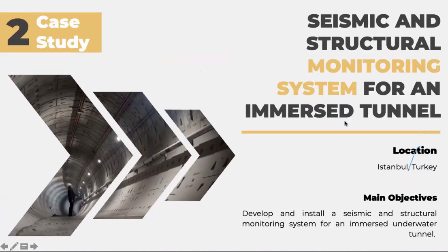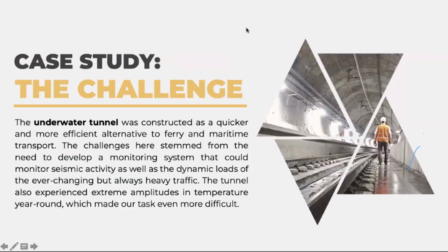Okay, so this is for the immersed tunnel monitoring in Turkey. The main objective was to develop and install a seismic and structural monitoring system for an immersed underwater tunnel. The challenges here stem from the need to develop a monitoring system that could monitor seismic activity as well as the dynamic load of the ever-changing but always heavy traffic inside the tunnel.